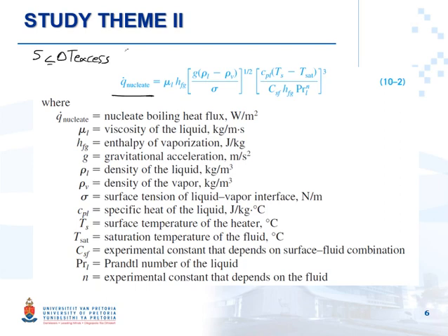We can use this correlation, and each term is defined here. You see viscosity of liquid, enthalpy of vaporization, density of liquid, density of vapor, and all those units as well. Surface tension, specific heat, liquid surface temperature, saturation temperature, an experimental constant which depends on the surface-fluid combination, Prandtl number, and another experimental constant.